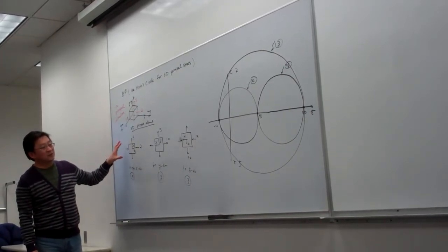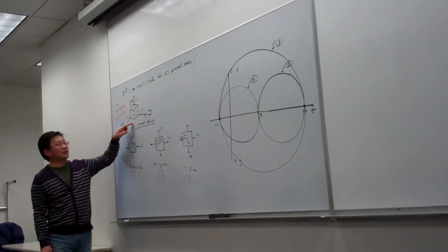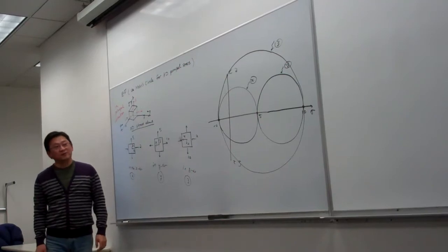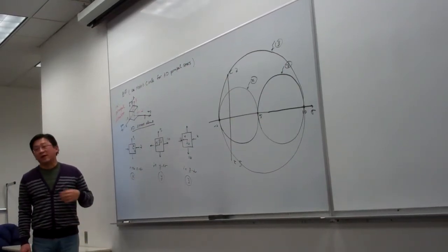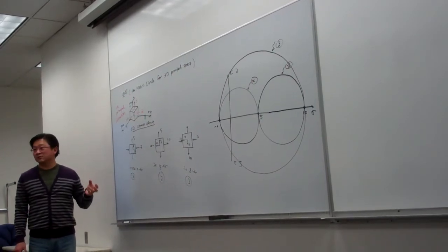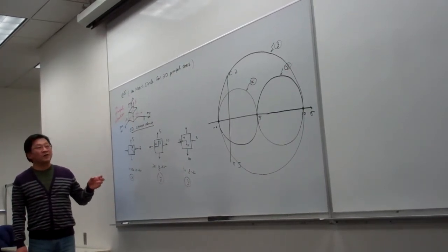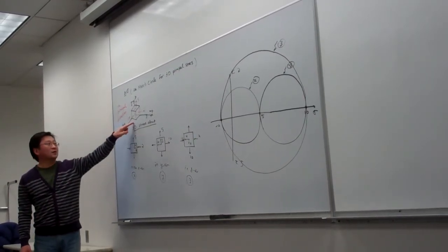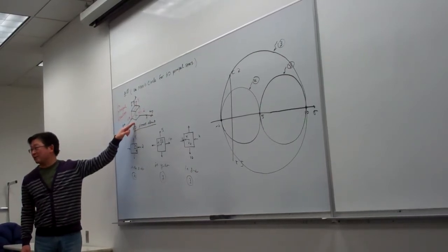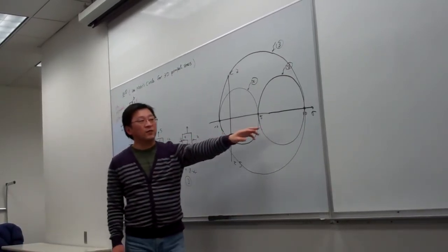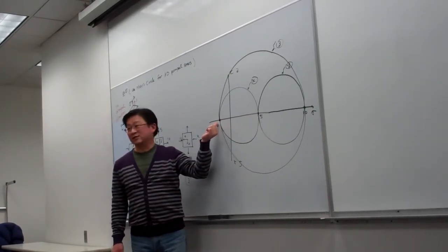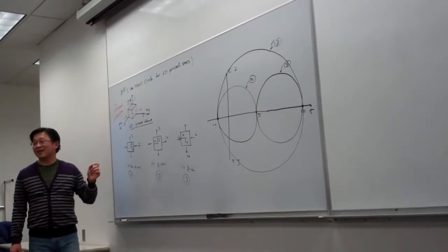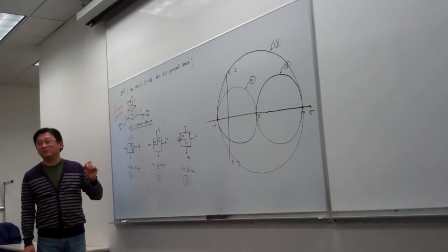So here we use 3 circles to represent this 3D element. And using these circles, we can quickly answer the question. Let me ask you, what is the maximum principal stress? What is the maximum normal stress for this example? 10. And what is the minimum principal stress? That's -2. And what is the maximum normal shear stress here? That's 0.